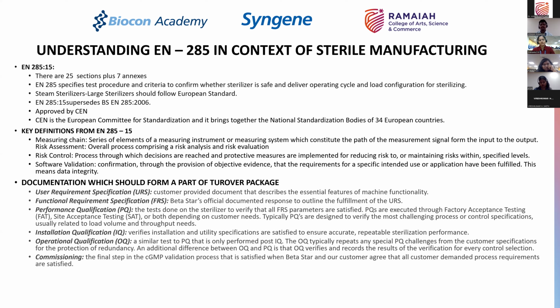So generally, as a rule of thumb, it's not a necessity, it's not a guideline. The factory acceptance test would include any kind of test which is sufficient for you to make sure that your equipment which is being supplied meets the user requirement specification and the DQ, and where the further action or rectification cannot be taken at your site.